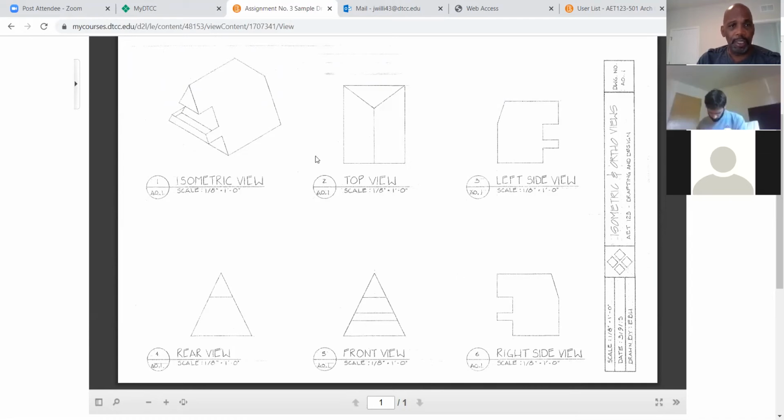So if you look at the isometric view here, this is the front, three-dimensionally, but when you look at the orthographic view from the front, which is right here, you're only seeing this building in 2 dimensions, as if you were standing at the building. So you would see that surface, which is this surface, that surface there, which is that one, and this one, and that one.